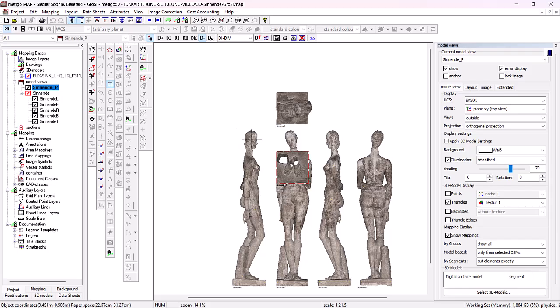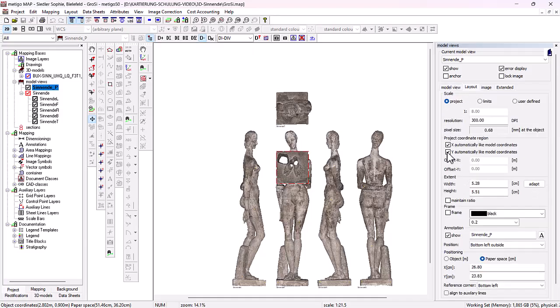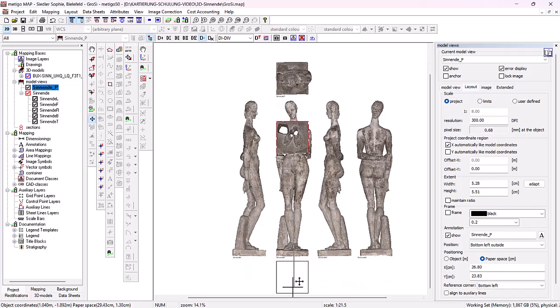Then I see my plate up here. I want to push it down from the position. And go to the tab layout. That means now the right value and high value are still fixed, so I couldn't move them at all. I turn off the high value, activate the move command, and can now move it as desired. I press the shift button because I want to move it down, and now I have here the top view of my footplate.